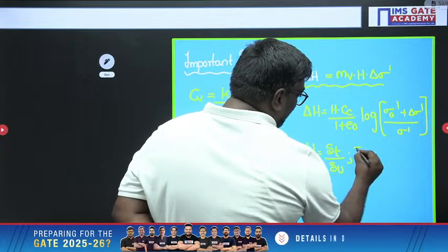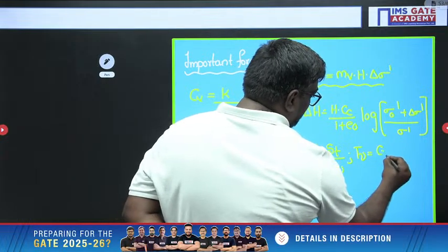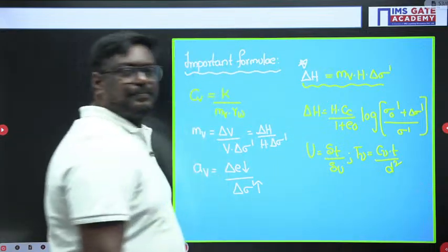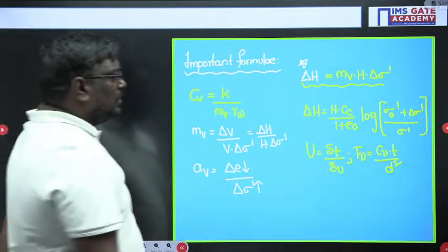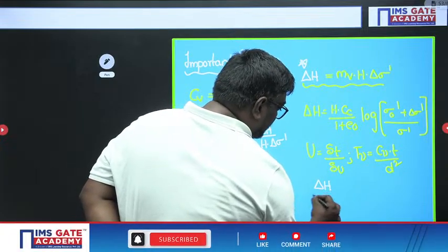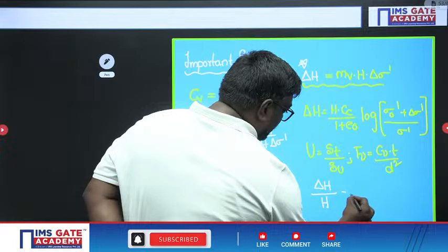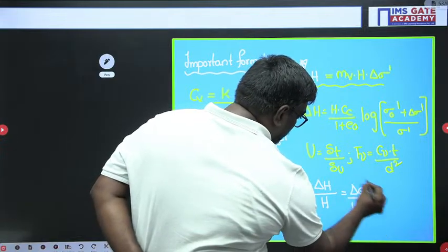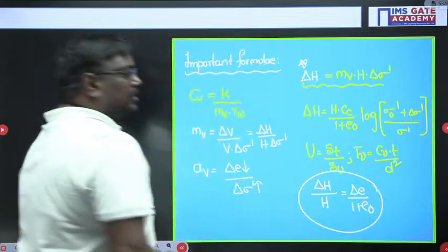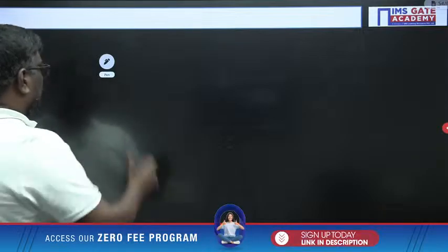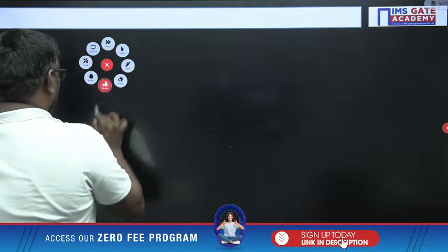And you know time factor is given by the formula Cv t upon d square. Now delta H by H can also be written as delta e by 1 plus e naught. This is another important relation. Now see students, let me explain some kind of problem where they usually ask, sir.